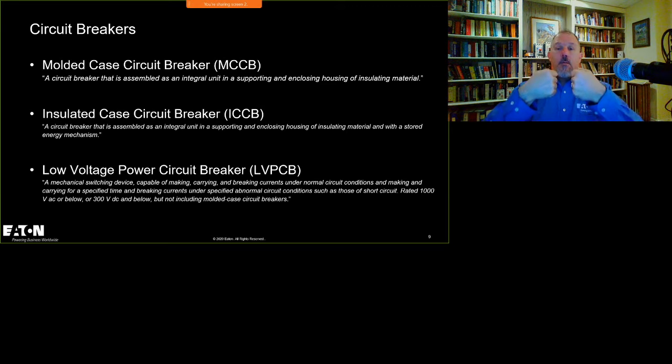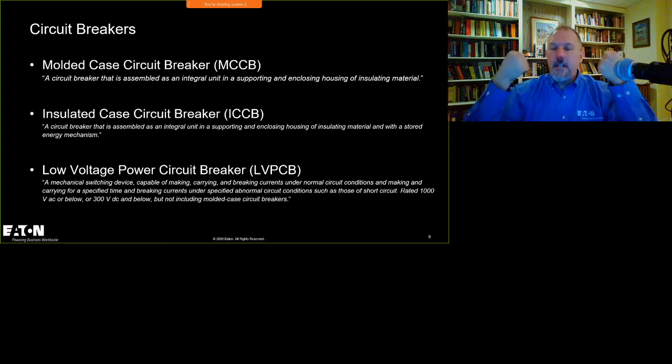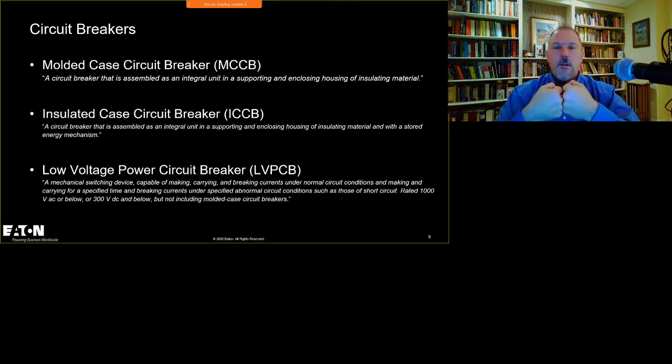We want to know how much current I can hold those contacts closed as I ramp that fault current up, and I want to make a clean break. I don't want chatter. Some manufacturers will permit that, so you have to be careful. If you get chatter inside that breaker, you can put dimples on your contacts, and that is, what's that called? Ungood.